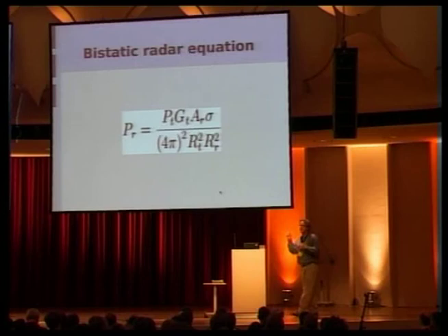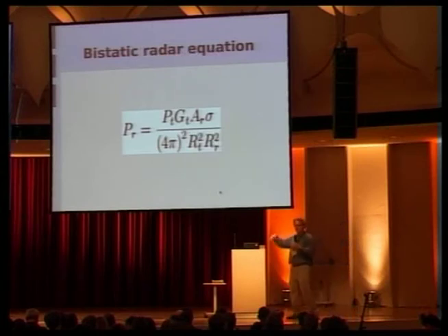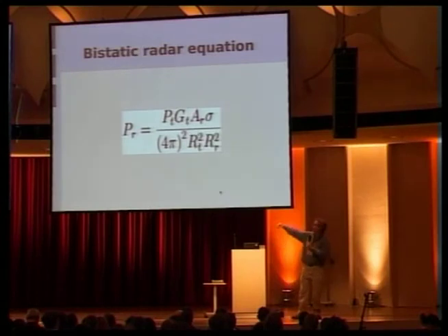Where this comes into play is you're trying to figure out how good the RF performance, the radio performance, needs to be, and how this performs in a noisy environment. And also, since the farther away everything is, you get this 1 over R squared basically loss. So the return signal falls off pretty badly.